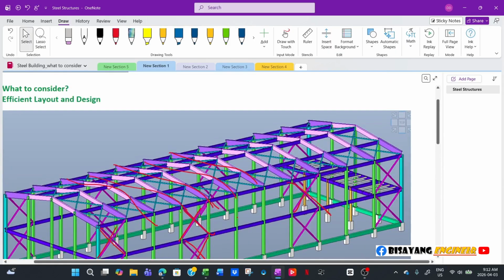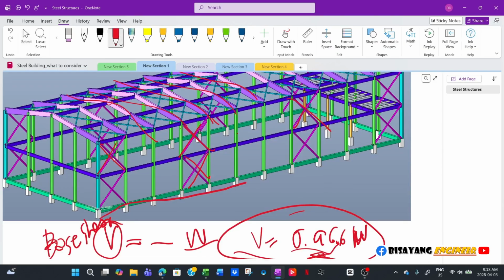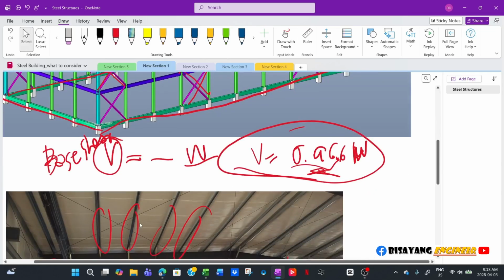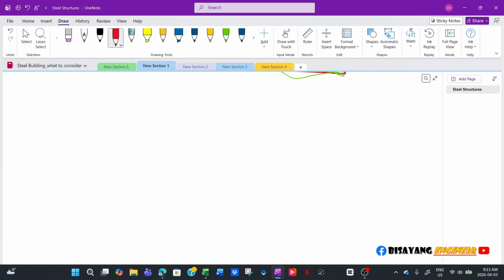And then I told him, when it comes to this one here, what exactly is the purpose of that one? And is that grade beam supported by the ground or is that suspended? When I say suspended, I already discussed this before. In cold climate, your grade beam is always suspended, and when you form that one, you only put a void form here.